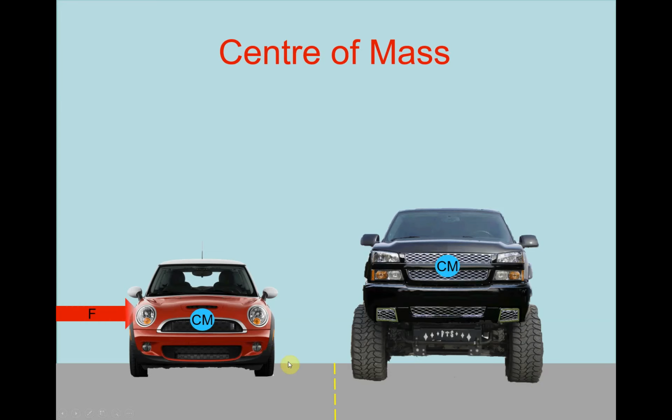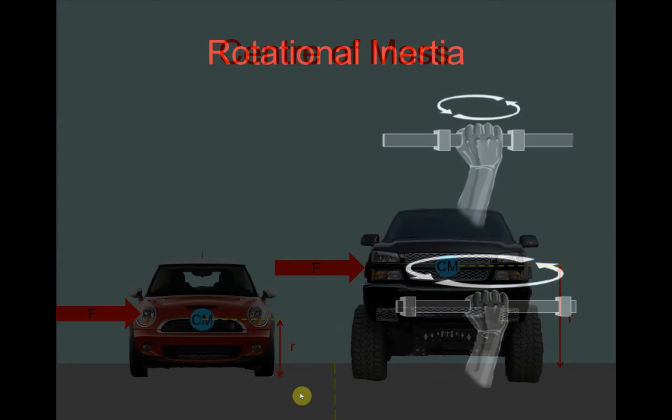That means if a force is applied to the side of these two objects, the lever arm moment, which essentially will be this force multiplied by this distance, will be much stronger for this object than for this one, causing this vehicle to flip and this vehicle to probably translate to the side. That's why sports cars are low to the ground and trucks tend to be higher. So if we were looking at the twisting force, which is the force about this point on the vehicle, we would have to look at F times R to the center of mass of both objects.